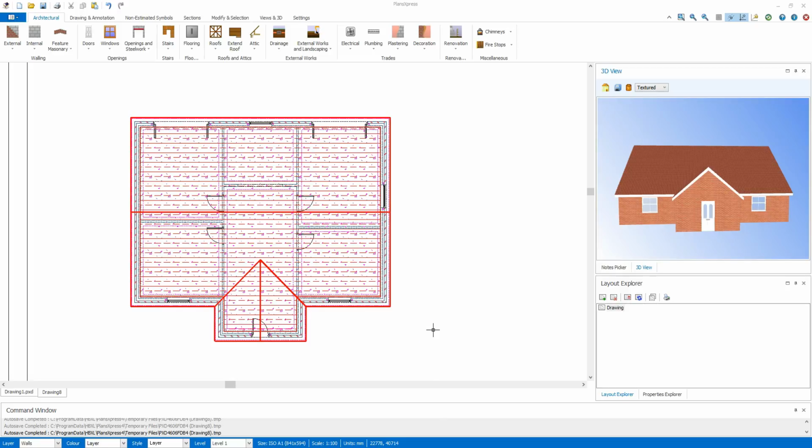In the previous video, we created this bungalow. In this session, we're going to look at construction lines, creating elevations, and adding details to those elevations, including heads and sills, trees, people and cars, and so on. We'll then have a look at dimensioning, and finally, adding labels to the drawing.